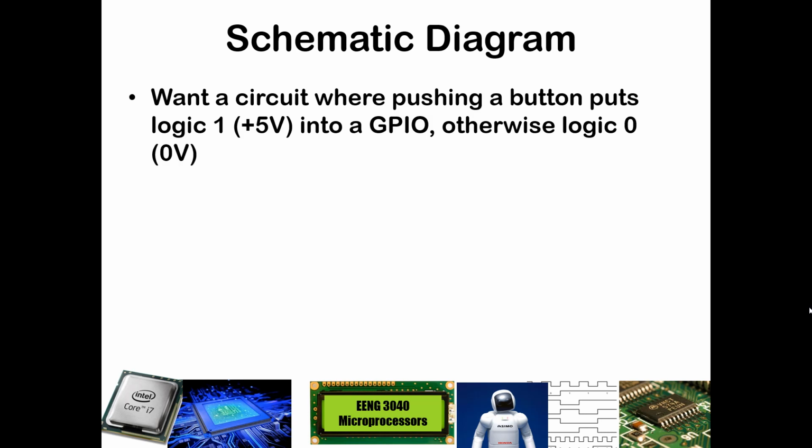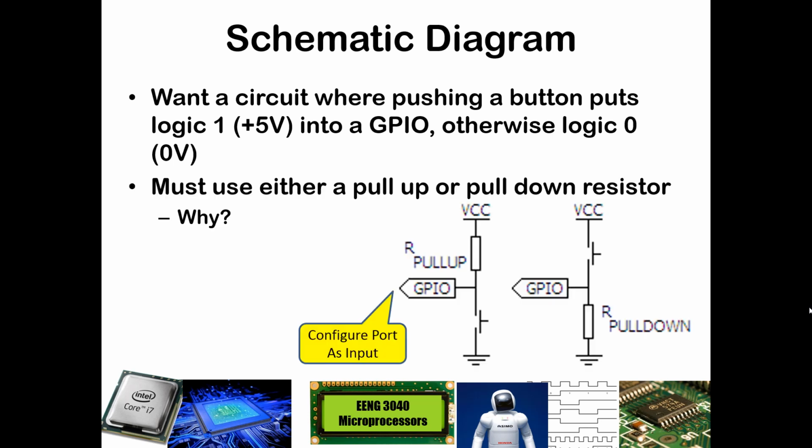The first thing that we want to note is that when you are working with these circuits, you will want to establish a 5 volt and a 0 volt reference. This will be to distinguish whether something is outputting a logic high or a logic low. Logic 1 will typically be 5 volts. In the case of some microcontrollers, you may have a lower power microcontroller operating at 3.3 volts or some other voltage level, but in these examples we will use 5 volts.